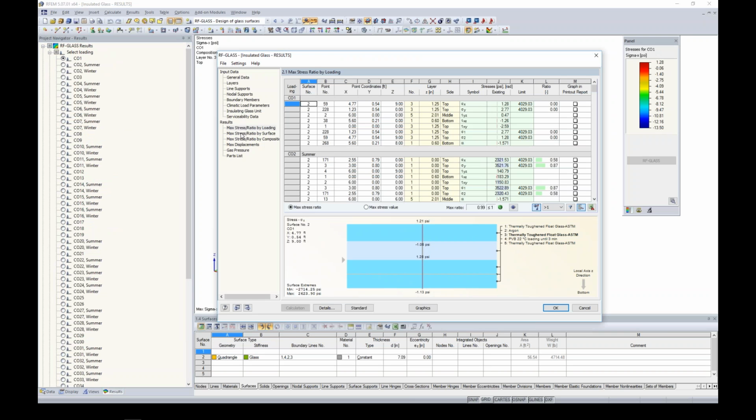Nothing really too different from our plate. Obviously, we're going to have more layers here for our stresses. You can see my max ratio is 0.99. Maybe for design, this is a little bit high. We wanted something more like 0.9. Regardless, we still get our green smiley face because we are under 1.0. Again, feel free to export any of this data into Excel.